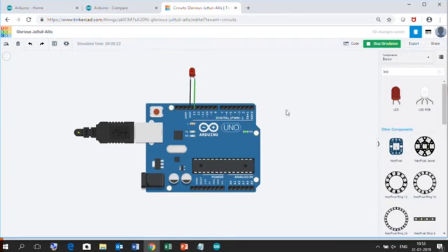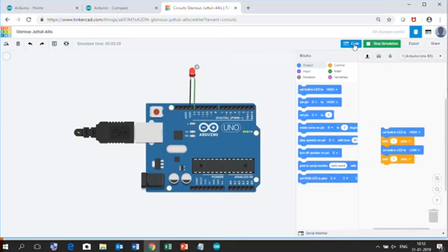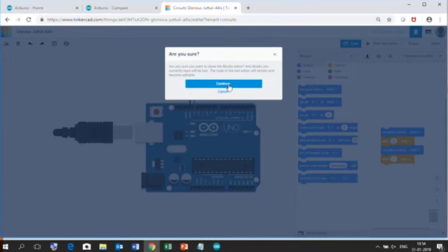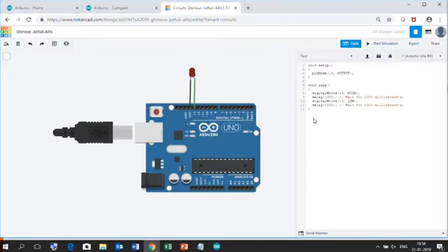After having this particular visualization of the circuit, can I go to the code tab here? I clicked on it. Let me stop the simulation. Stopping the simulation, it has removed the plugin. Under the code blocks here, pick up the drop down text. Let's say continue. Hey, it has highlighted the code. Isn't it familiar to you now? The setup method, loop method, using that digital write on the default pin number 13, all that I could do this.